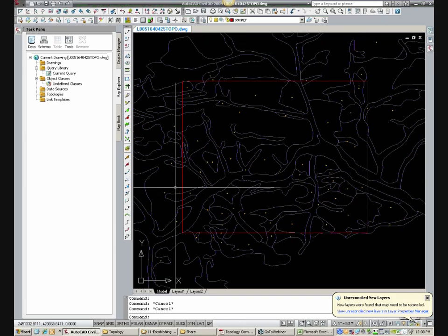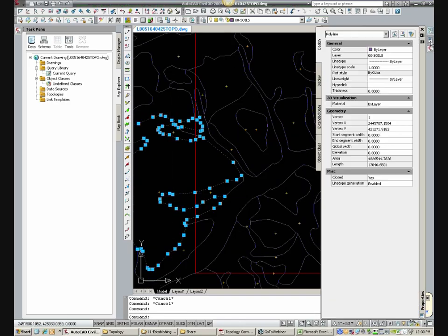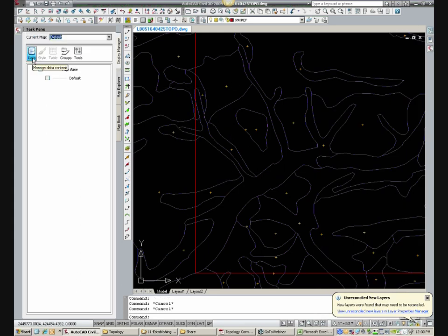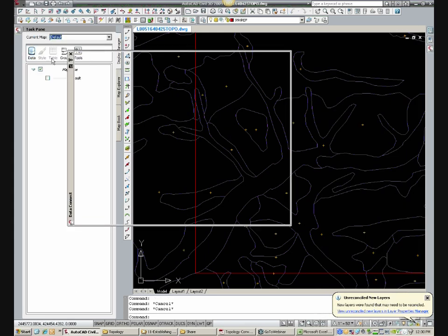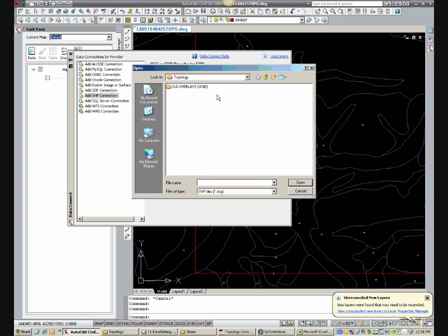And really what gets you messed up is that when I click this polyline now, since I ran that Create Centroids command, it doesn't have any more object data assigned to it. So how do I do this efficiently? Well, I can come up to my Display Manager, hit Data, Connect to Data, and connect to the physical shapefile that was read to bring these soils in. I'm going to call this Berks Soils. This is a little workaround, but it seems to work pretty well for me.